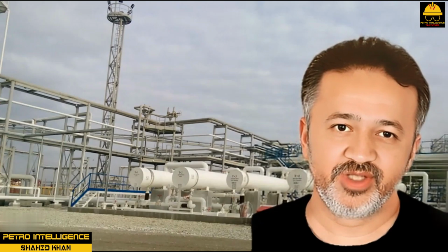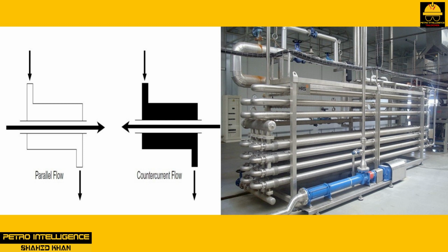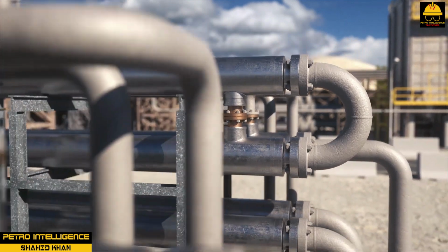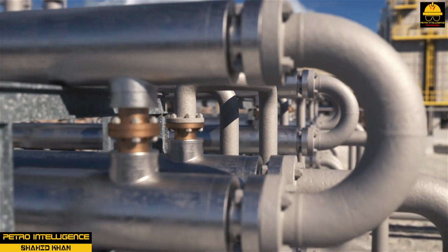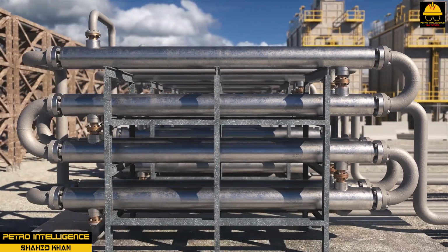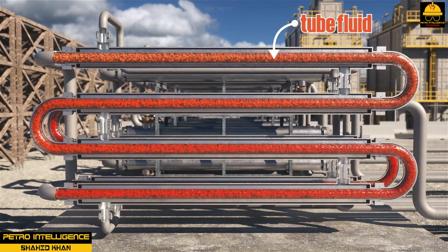Double pipe heat exchanger. A simple design for heat transfer is found in a double pipe heat exchanger. A double pipe exchanger has a pipe inside a pipe, as shown in picture. The outside pipe provides the shell, and the inner pipe provides the tube. The warm and cool fluids can run in the same direction, parallel flow, or in opposite directions, counterflow or countercurrent. Flow direction is usually countercurrent because it is more efficient.